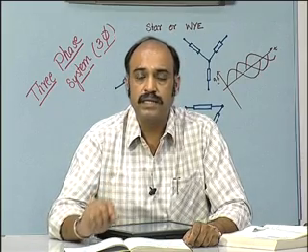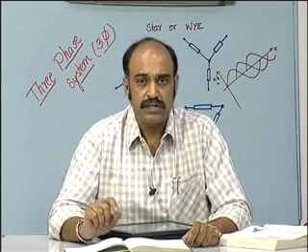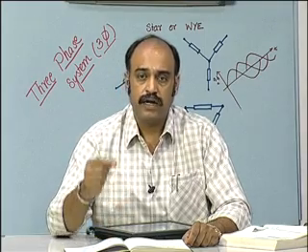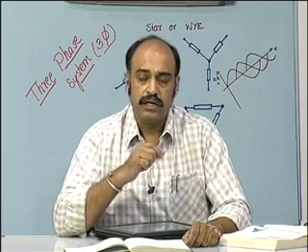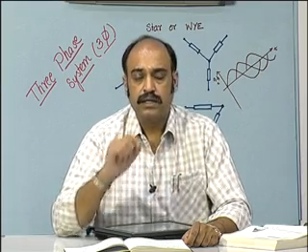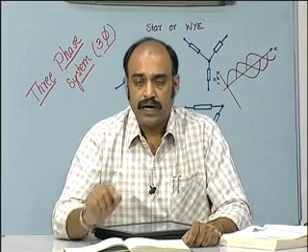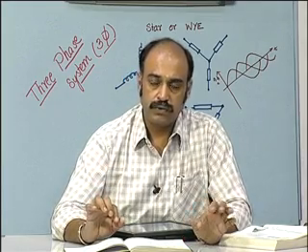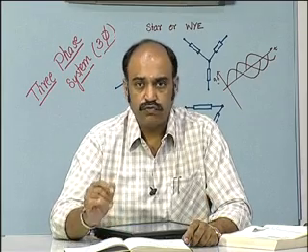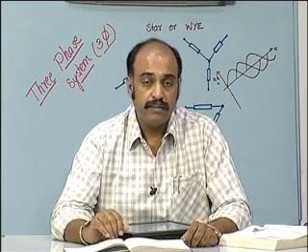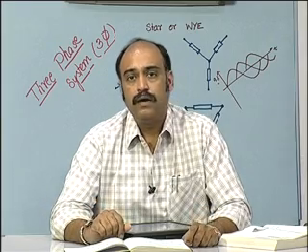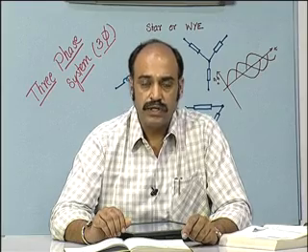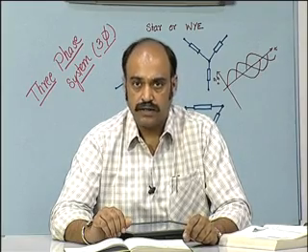However, if the load is unbalanced, then IA plus IB plus IC is not equal to 0, and therefore we need to provide a return path from the load side to the source side, and that return path is through the neutral wire. Under such conditions the neutral point of the load and the neutral point of the source are connected, and it becomes a 3-phase 4-wire system. Under unbalanced conditions, if the neutral connection is not provided, then there will be distortions in the voltage wave shapes of the 3-phase loads.